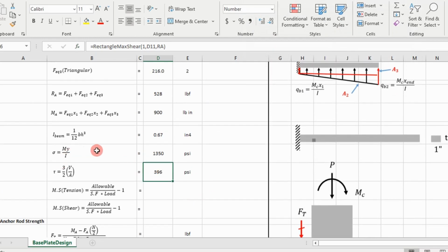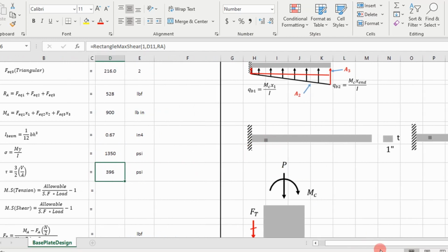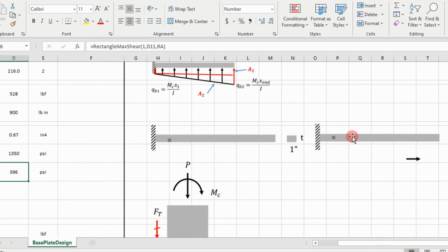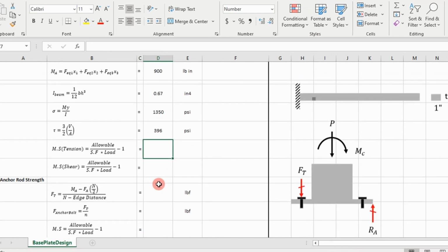So we have calculated our stress values for those two situations, the bottom of the stress element and the stress element at the middle of the beam. Now we have to calculate margins of safety for both. So we're going to use, when you're looking at just a stress element under tension, von Mises stress. Basically your allowable from von Mises stress is going to be your yield stress.